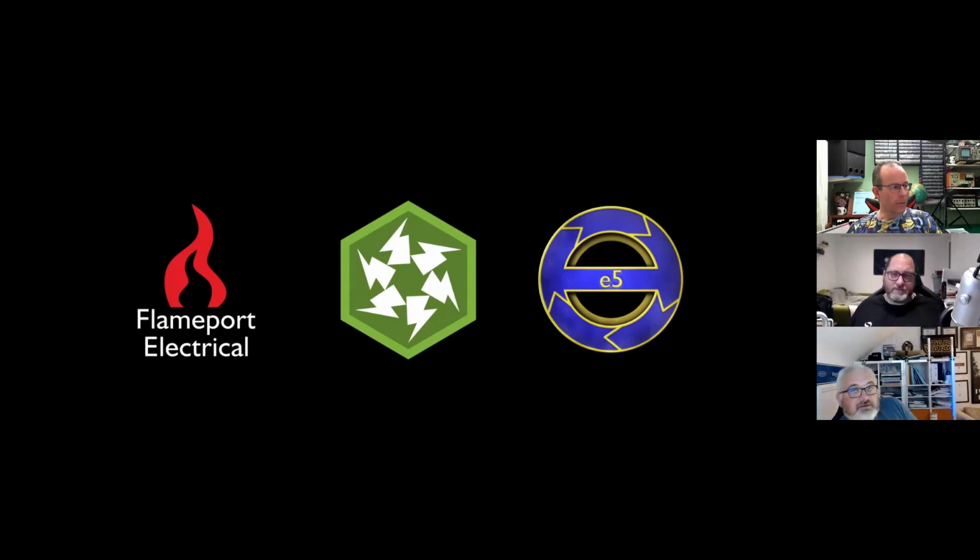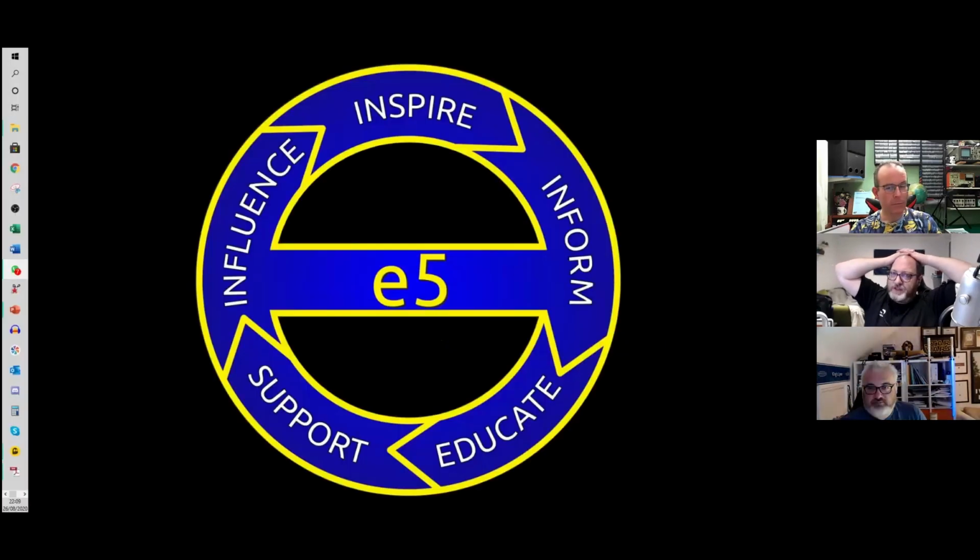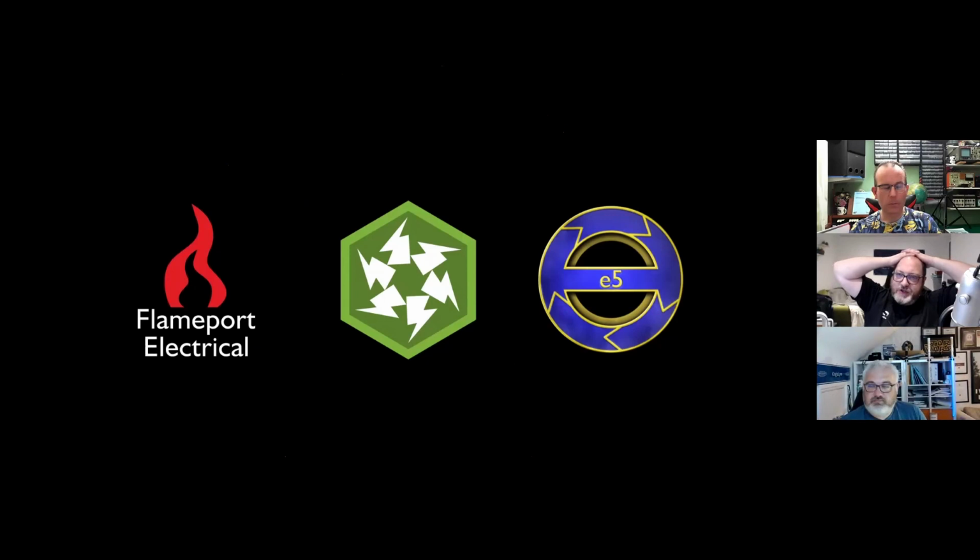The other one from Simon Goodship is along the same lines. It's about bending radius. We've got tails entering the consumer unit, and bending radius does matter. If you check with the actual cable manufacturers, they'll tell you what the minimum is, and it's normally so many diameters of the cable. Exactly. The manufacturers will give you specifications about that. The wiring regulations give you things under wiring systems where you've got risks of impact, and it mentions tension, compression, and things like that. And connections placing strain upon conductors. The fact of the matter is, there's a reg that says you must follow manufacturer's instructions. That includes cable ones.